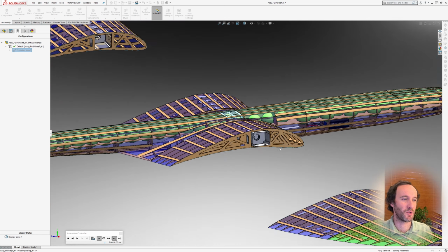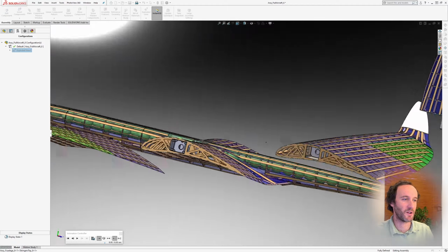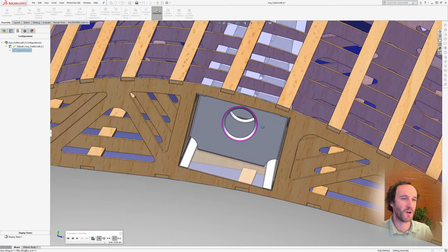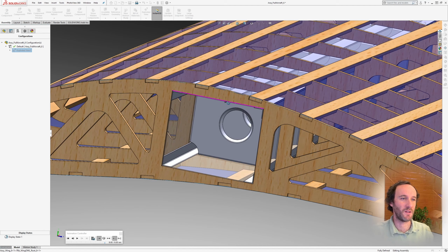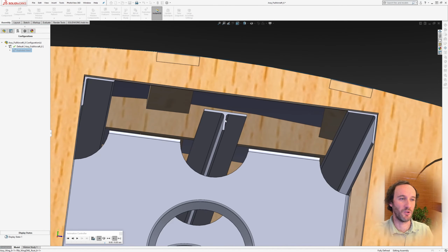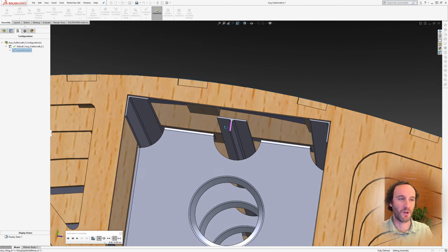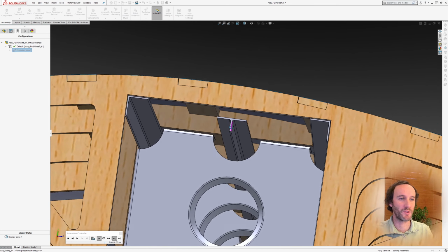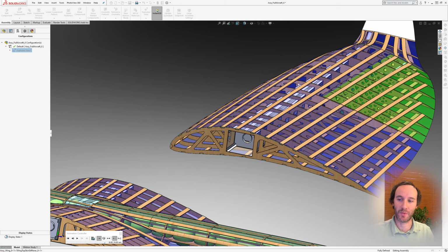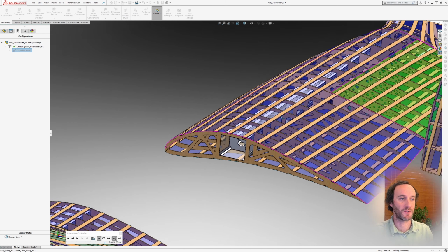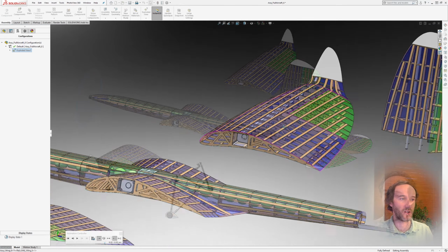For instance, in commercial full-size aircraft, often the spars will extend all the way to the wing surface, and then the stringers, which will be more like this aluminum T-section or another type of extrusion, those themselves will often bend and twist along the wing surface. And I'm sure there's lots of other applications where long, thin structural members bend and twist along surfaces.